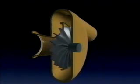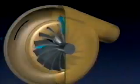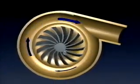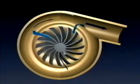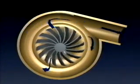As the high-speed impeller rotates, air enters the center. The speed imparts high velocity to the air as it moves outward into the diffuser. Here, much of the velocity is converted into pressure by controlling the deceleration. The high-pressure air is collected and flows to the outlet.